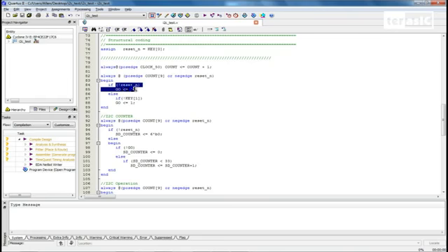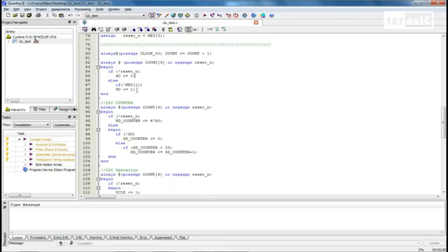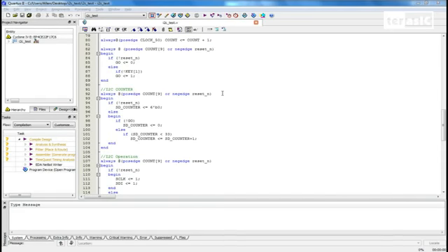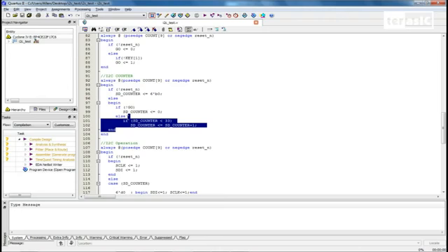Over here we can see that every time we reset, our go will equal 0. If we press our key 1, then our go will equal 1, which starts our I2C communication. We can also see that we've set an I2C counter, and what it does is form a sort of lookup table for us to base on what to do during our I2C operation. We'll get into that later.